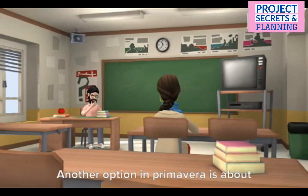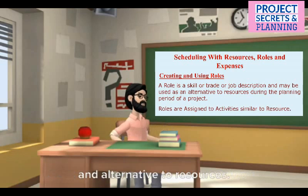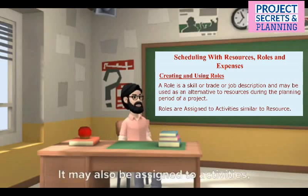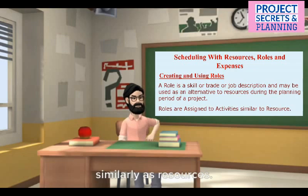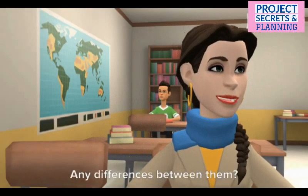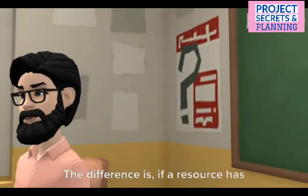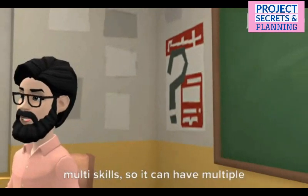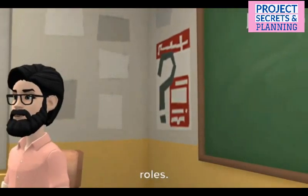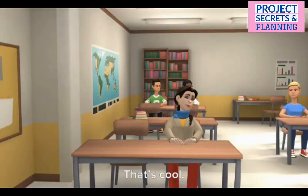Another option in Primavera is roles. Roles are skill or trade or job description, an alternative to resources. They may also be assigned to activities, similarly to resources. If they are the same, then why were both of them introduced in the software? Any differences between them? Good question. The difference is, if a resource has multiple skills, it can have multiple roles. For example, a planning engineer is also a document controller, so this resource would be assigned 2 roles, planning engineer and document controller. That's cool.